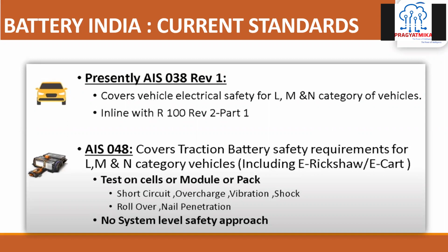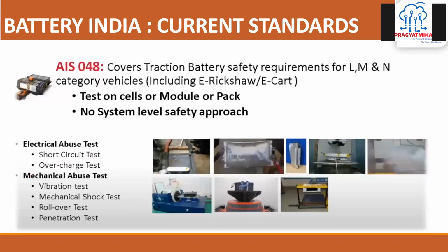And a system level approach is not yet in the AIS 048. It is the cell level approach that is still followed, like short circuiting, vibration, shock analysis, penetration tests. So at a cell level, these tests are performed, not taking the whole thing as a system, not complete battery pack level tests. Thereafter,